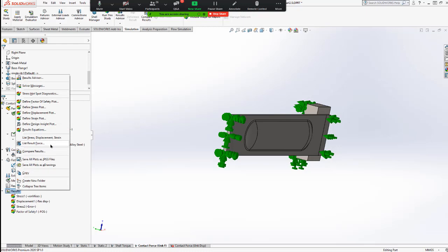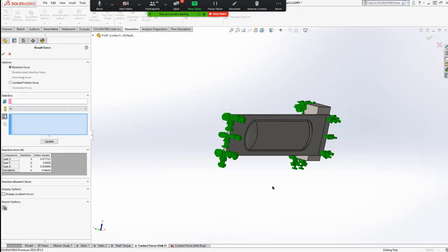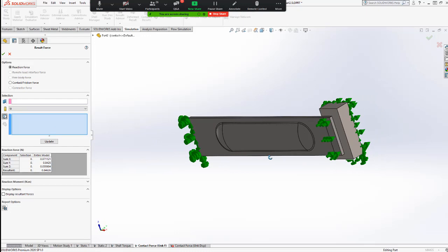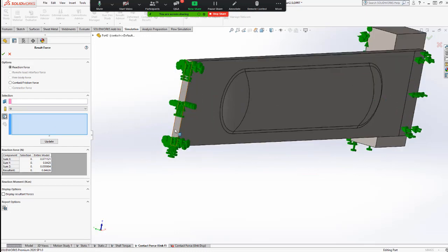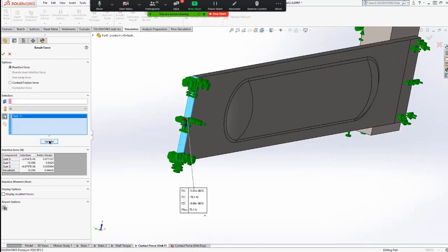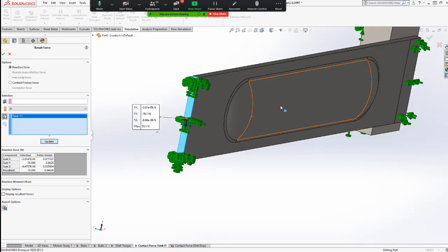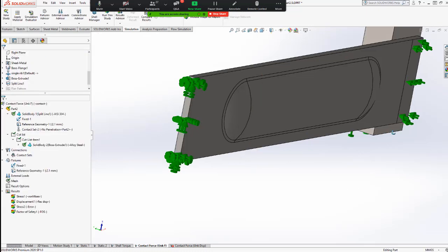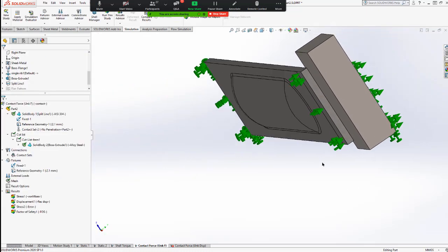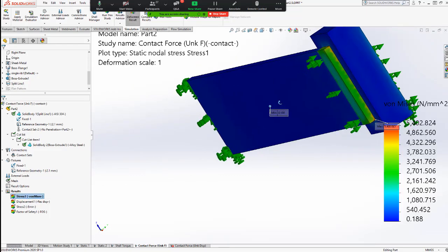For this, we're going to check out our result forces. And let's just check this again. See how things are going. Remember that rib's going to have a lot more internal resistance to moving, so there's going to be a lot more force needed to move this 2 millimeters, so that is going to be how much we are getting, 78.1 newtons as per its geometry.